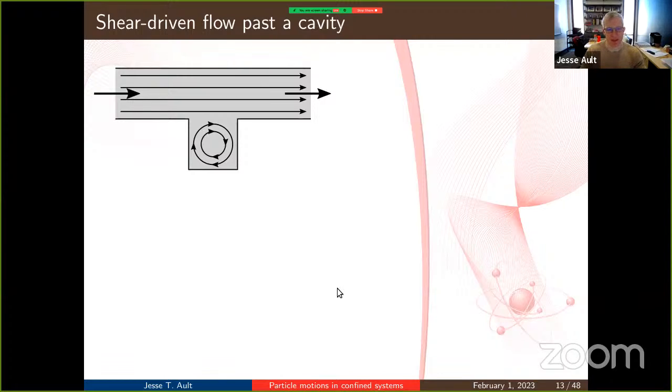So the reason we looked at this is essentially, it's a very basic geometry. It's been widely studied in the 2D literature. When you introduce 3D effects, you know that you have some source of swirl inside the cavity, and maybe you also have an axial component of flow along the vortex core in 3D. In 2D, obviously you don't. And so that begs the question, can there be a regime where this swirl number, which is an important criteria for the onset of vortex breakdown, is there a swirl number in these cavity flow problems that can trigger the onset of vortex breakdown? So this is what we wanted to look into.